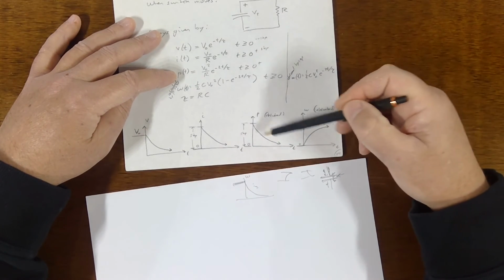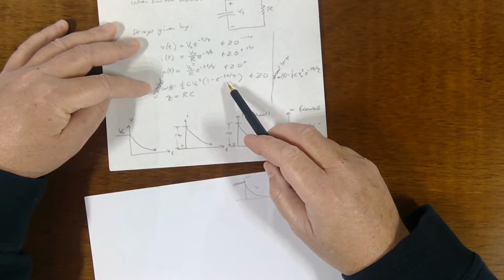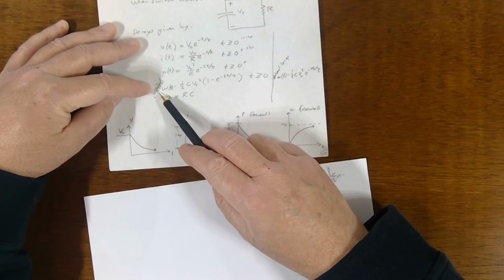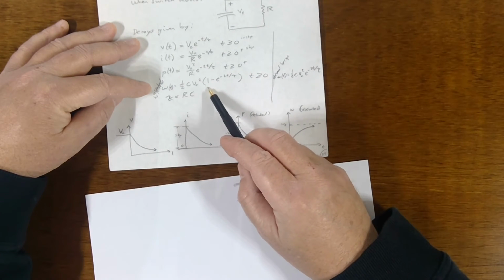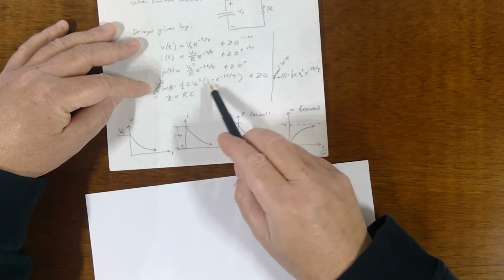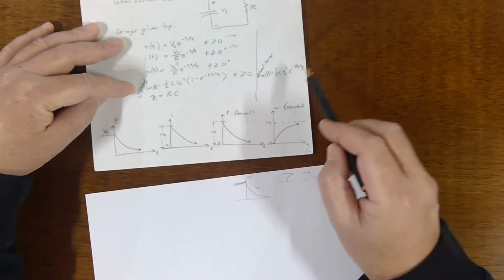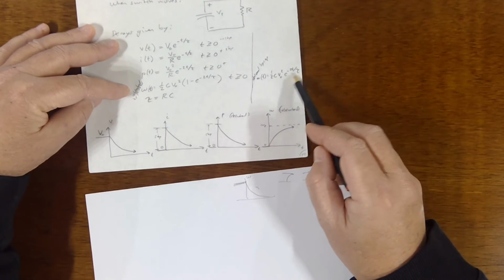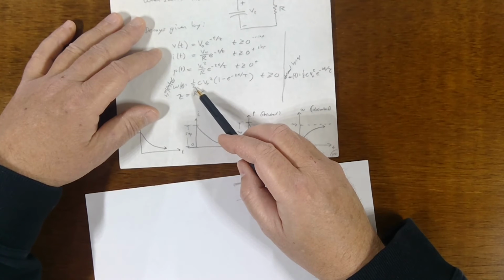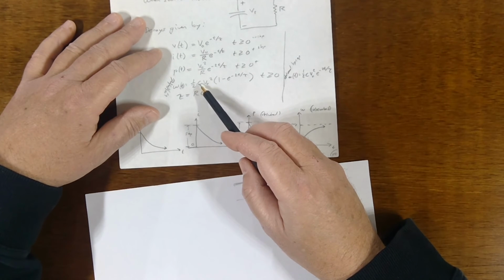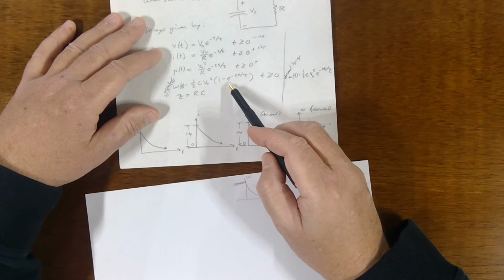That's this thing. And then here's the energy equation from two perspectives. If it's absorbed by the resistor, then this decay envelope term has this format, and if it's delivered by the cap, it has this format. But it's a variation on our general energy equation, 1/2 CV squared. It's just that V is a function of time here.